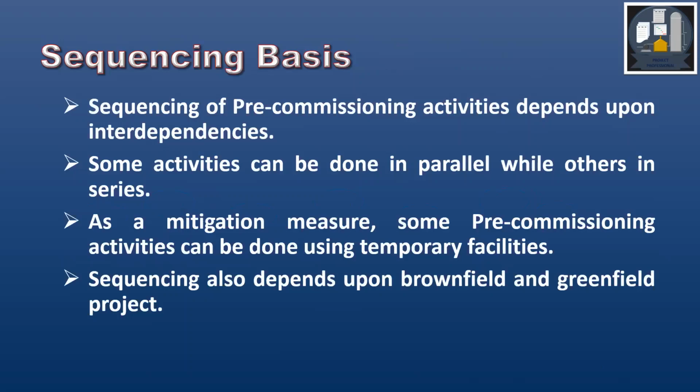Sequencing basis. Sequencing of pre-commissioning activities depends upon interdependencies. Some activities can be done in parallel while others in series. As a mitigation measure, some pre-commissioning activities can be done using temporary facility. Sequencing also depends upon brownfield and greenfield project.